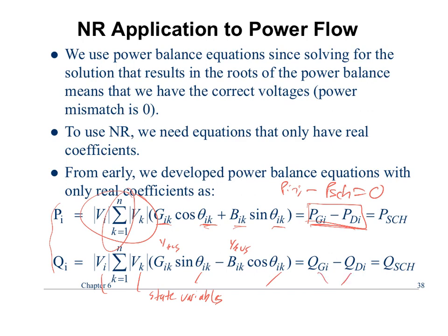And then these two are from the model, essentially. So that's the load that you have, the load or the supply at a particular location. Are G and B given values? They're going to be in your Y bus. So you might have to create Y bus, because that's chapter 2. So you can build Y bus, or it'll be given to you.